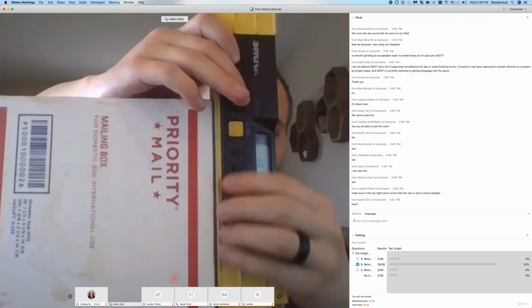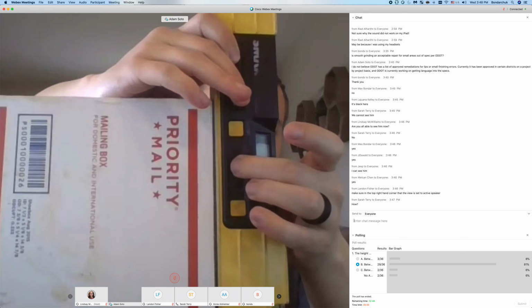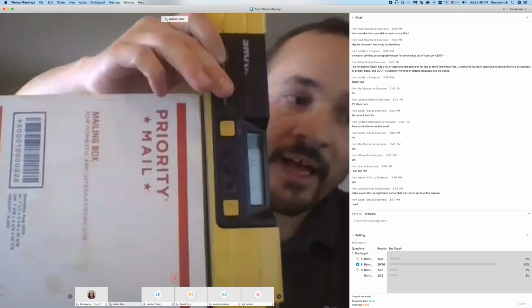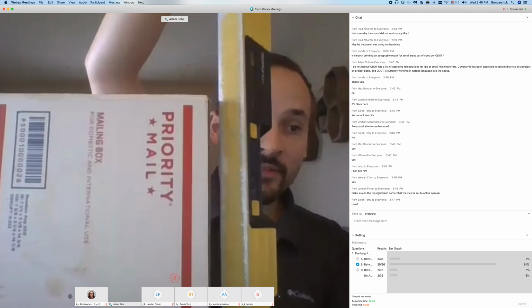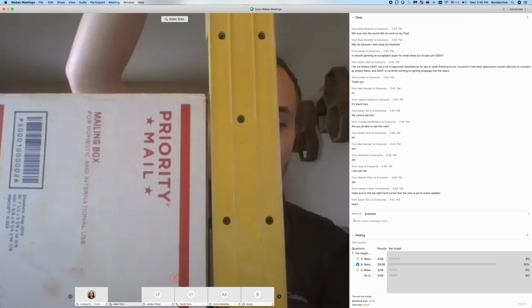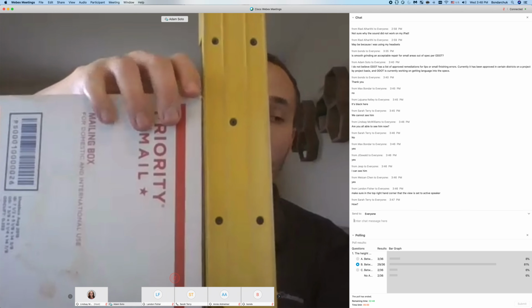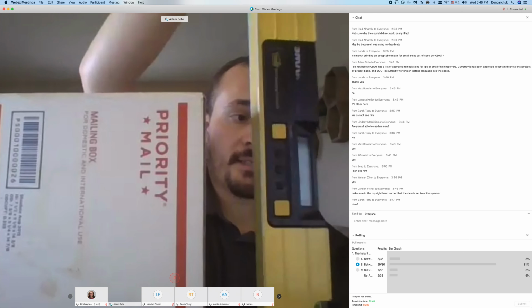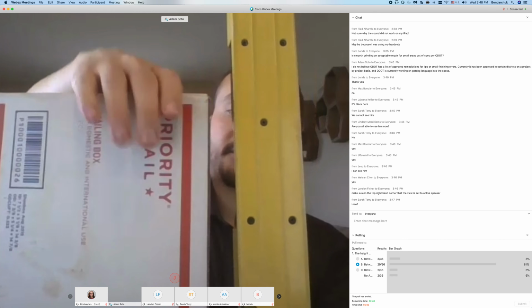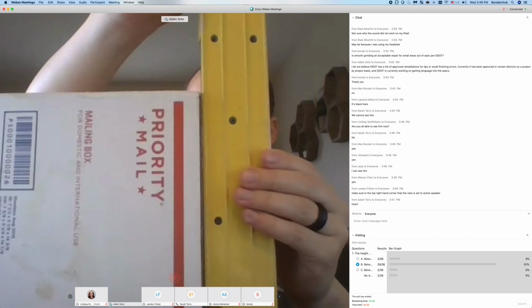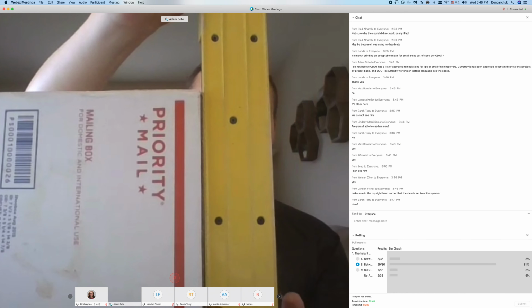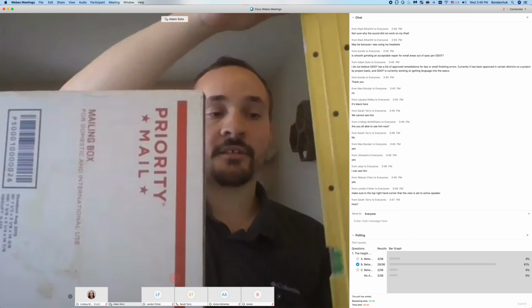And so we'll press and hold the middle button, and it'll start to flash. And now we're going to twist it 180. So the bubble is still on the bottom. A lot of people mess up that step. It's a twist 180 to get the second measurement once the screen is flashing. And then once it flashes the same number 3 times, you press the middle button, and it'll say Cal 2, and it'll stop flashing.